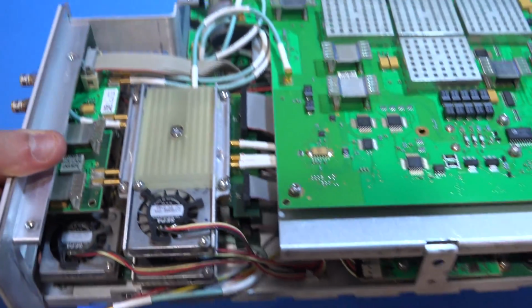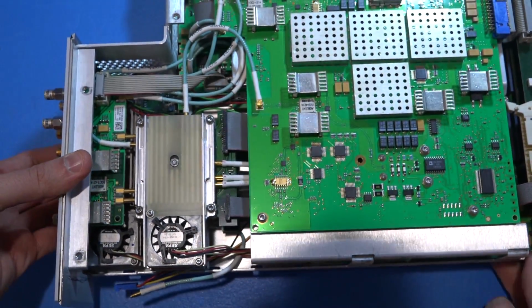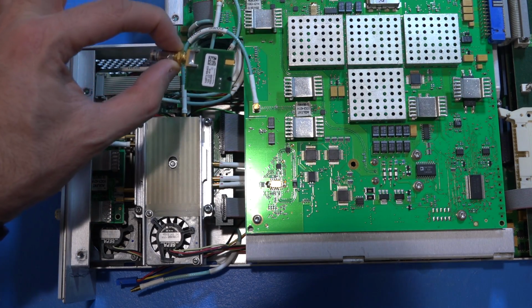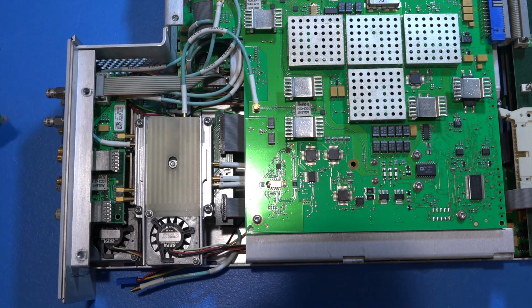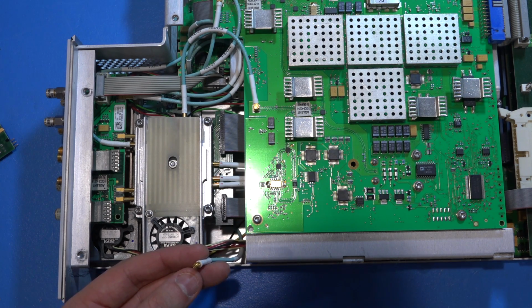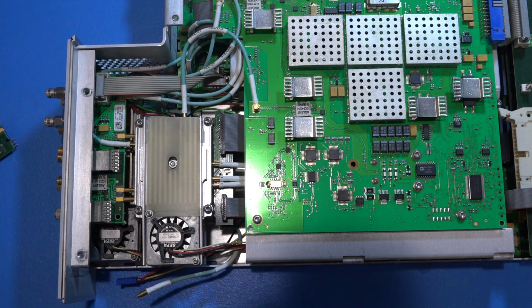So what are some of the things we can try to make sure that that's not the case, or to isolate the problem further? Well, I'm going to have to put this back in the unit, bring these connectors raw outside of the unit from the front little hole that's there somehow, and basically test this front module separately. This will allow me to measure DC voltage at the input of this and see if there is any back voltage coming out indicating a damaged circuit on the input. And that's the first step.